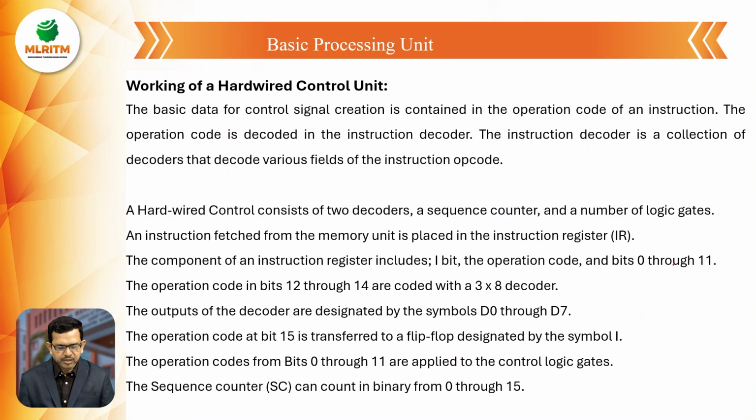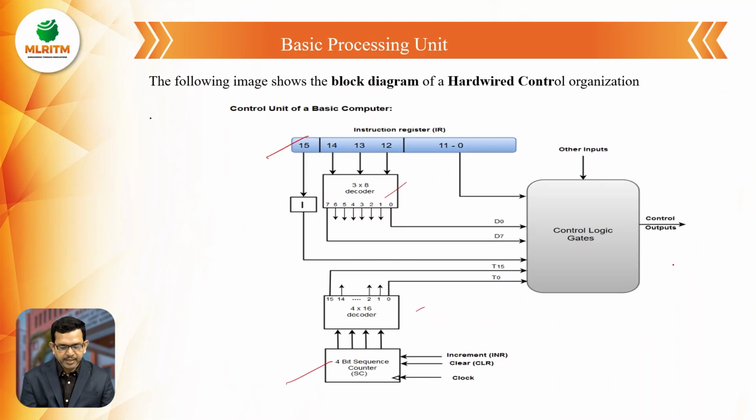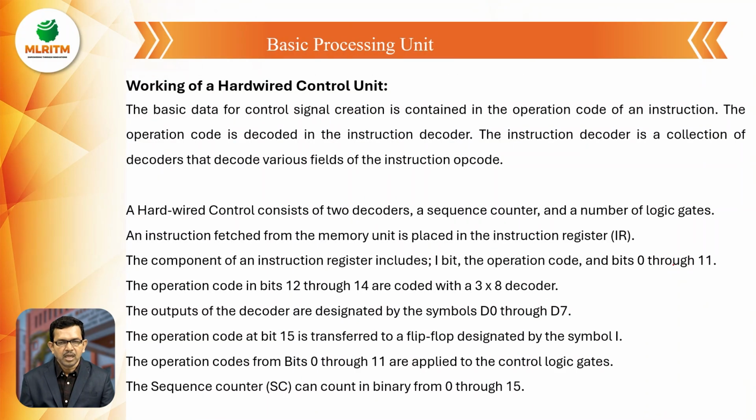Coming to the next slide, we will try to see how the hardware control unit is going to work. In the previous slide, we saw the complete components, the complete registers and the decoders which we are using. Here we will try to discuss how these are all integrated and transfer the instructions, or transfer the input, to the control logic. If you go to the working of the hardware control unit, the basic data for control signal creation is contained in the operation code of an instruction.